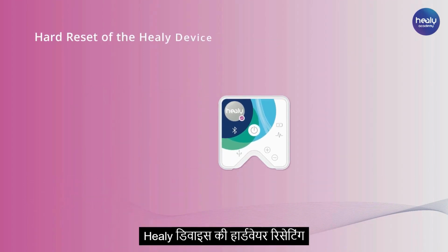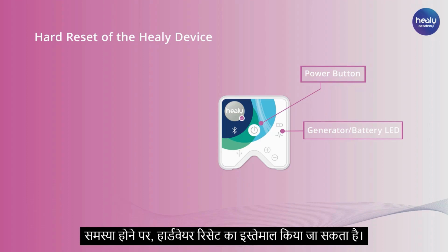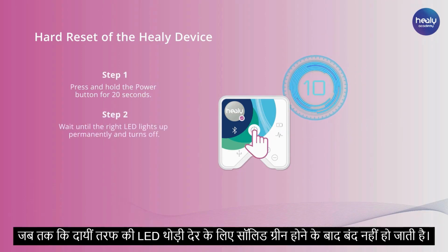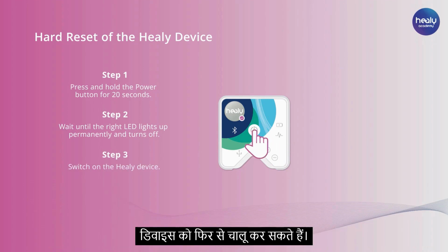Hard reset of the Healy device. The hardware reset can be used if the Healy device does not respond or if you are having problems with the Bluetooth connection. To perform a hardware reset, you must press and hold the power button for about 20 seconds until the right-hand LED briefly glows in solid green and then turns off. Now you can turn on your Healy device again by firmly pressing the power button.